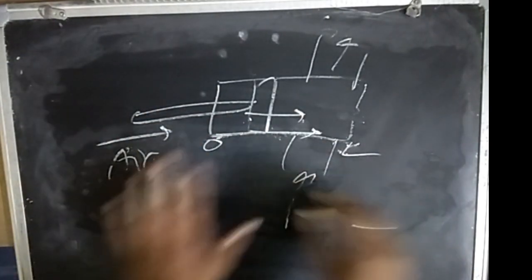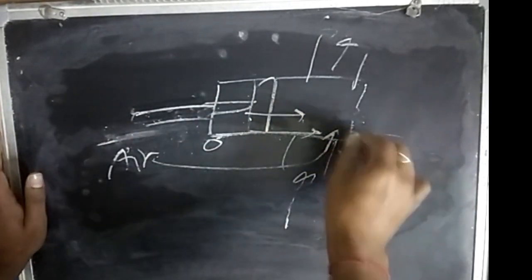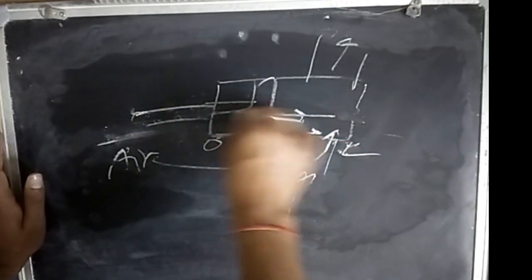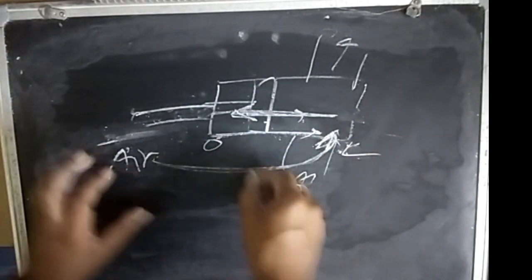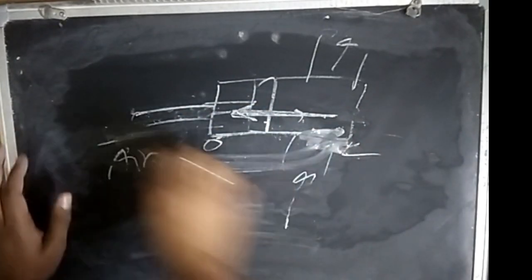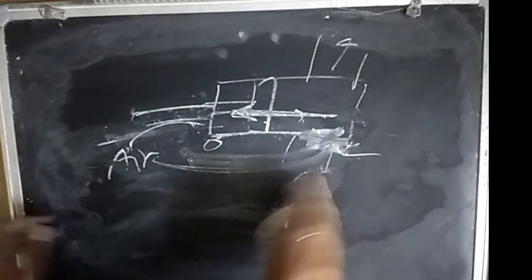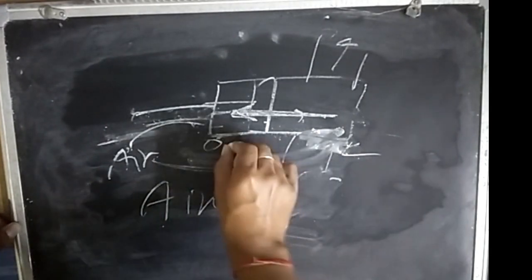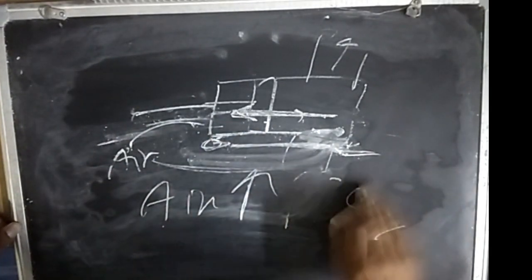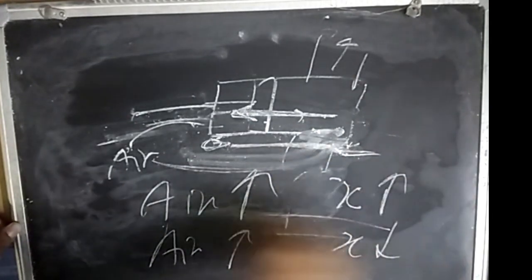So direct acting. If air to close valve, then I'm putting my air from the opposite side, and this air is moving this and opening this. But here my distance is reducing while my air pressure is increasing. So this is air to open valve, while the other one was air to close valve. And how about direct acting and non-direct acting? If my air pressure is increasing and my position, from 0 to L, also increases, that is direct acting. If my air is increasing but my position is decreasing, this is indirect acting.